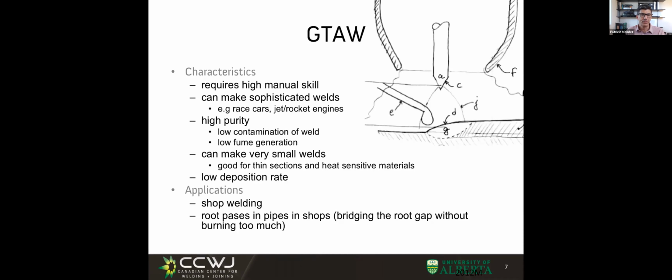And in the case of TIG, it's especially bad because also the tungsten might be exposed to oxygen, so everything gets ruined. So if we want to use processes that have a shielding gas, like TIG in the field, typically they make a shack around it to prevent drafts. And even if you make a shack, somehow drafts still come in. So TIG, much like all other gas shielded processes, tends to be a shop process and less common in the field.